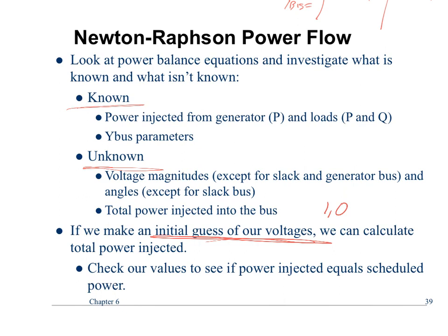How would it be if you have a system voltage at 34.5 kV up to 765 kV? That's a pretty big change, right? A value of up to 20 times. So doing everything in per unit, everything is around 1 at an angle of 1.1 radians, correct? So everything is going to be within 1 plus or minus 10%, or 0.1, so 0.9 to 1.1 for the magnitudes, and the angles are going to be between positive 2 pi and negative 2 pi.